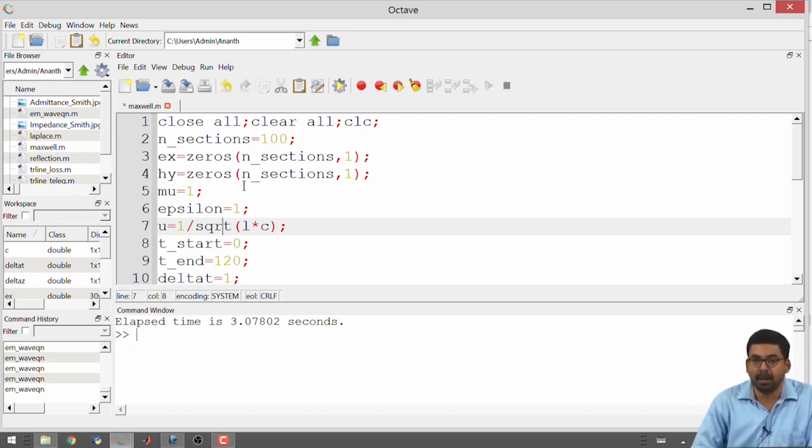It is a very tiny number. When you are using these numbers for multiplications, divisions, etc., there is a possibility that the result will be approximated to 0 by the computer. So, in order to avoid these approximation errors, it is better to do the simulations by considering only epsilon r and mu r, and maintaining the velocity equal to 1.